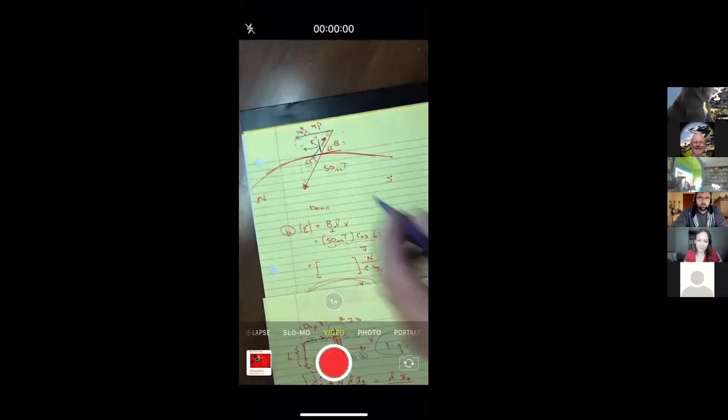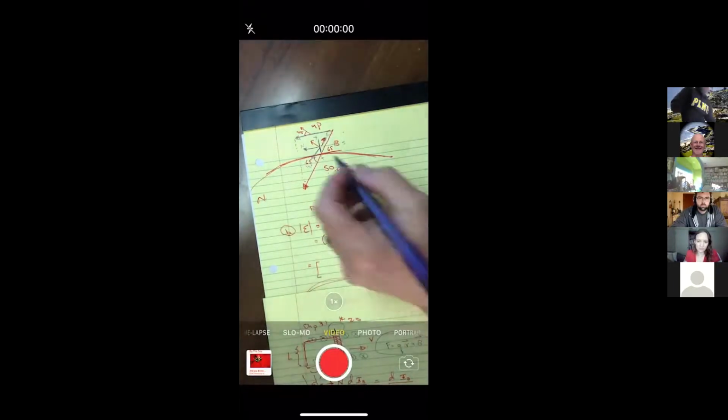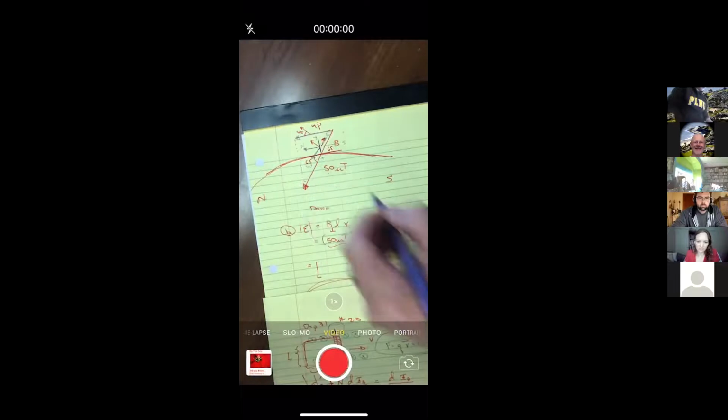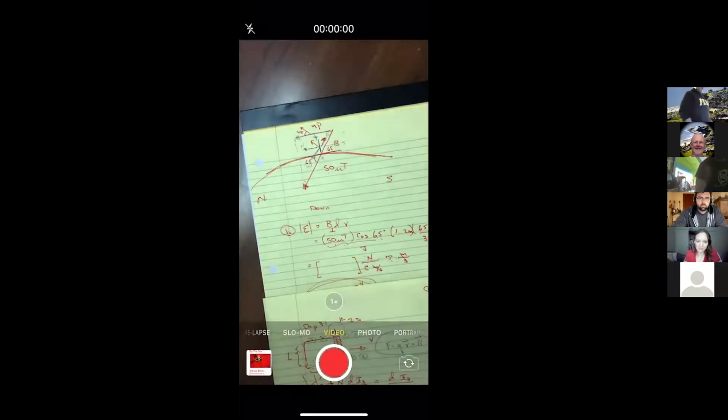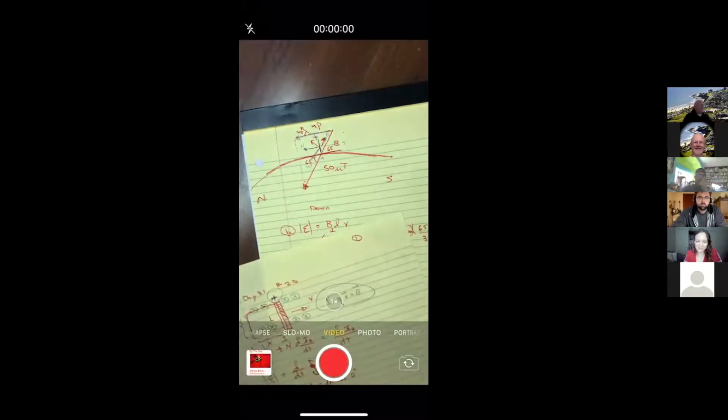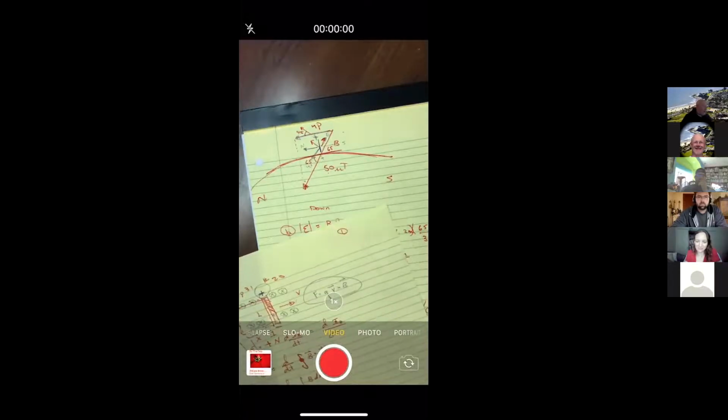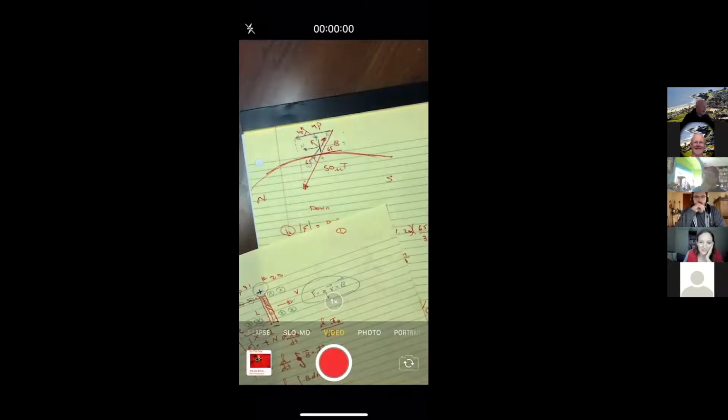My thumb would point down. That would push positives down. So moving to the west, the bottom of the antenna would get positive, whereas moving to the east, the top of the antenna would be positive. And they wanted the top to be positive. So there's my answer. I must move to the east. So moving to the east would give me not only the maximum, but it would give me the positive upright, or the top. Now that's for a vertical antenna.